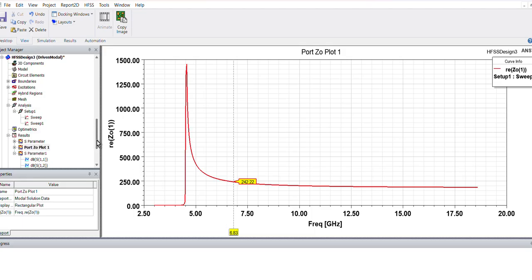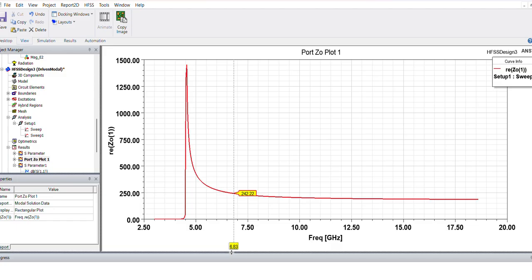Just like our cutoff frequency is scaled, our impedance is also being directly scaled. And that's a beautiful thing. So basically, we can bring down the impedance also by putting the dielectrics inside the same waveguide dimension. Right? Now, in the same dimension, what we shall do now, we shall actually try to make the same 8 to 12 gigahertz WR90 waveguide.